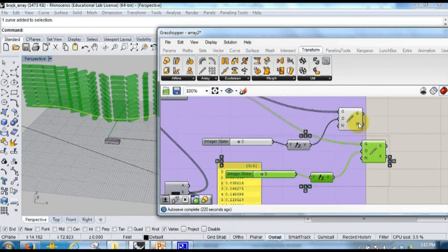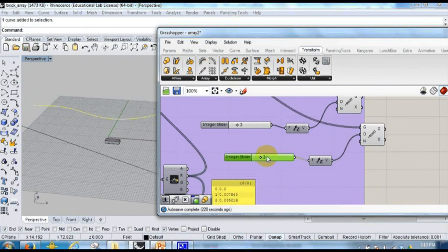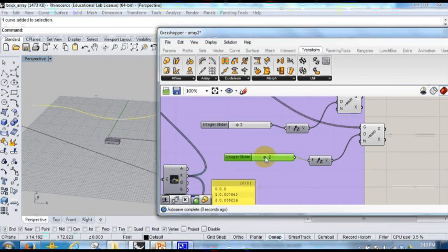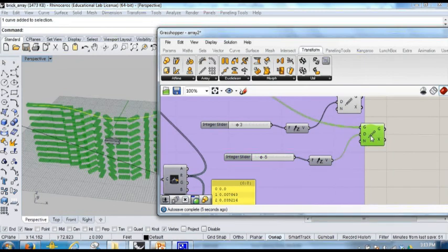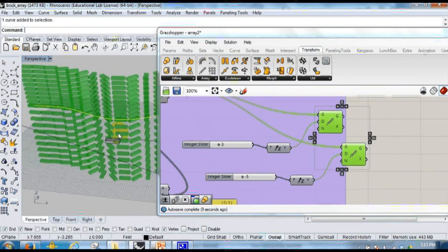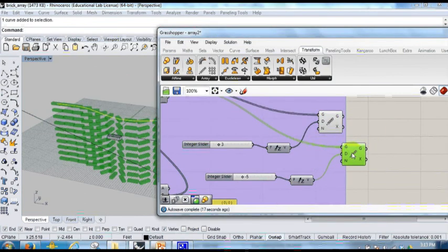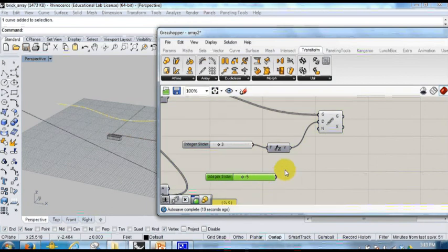Then for the second one, you give this guy -3. Oh, I should define the minimum value as negative. In this case, it will move the z down, and if I take a look at the result, you got this pushed down. If I highlight both, you got both. So sometimes you could add additional components into this process.